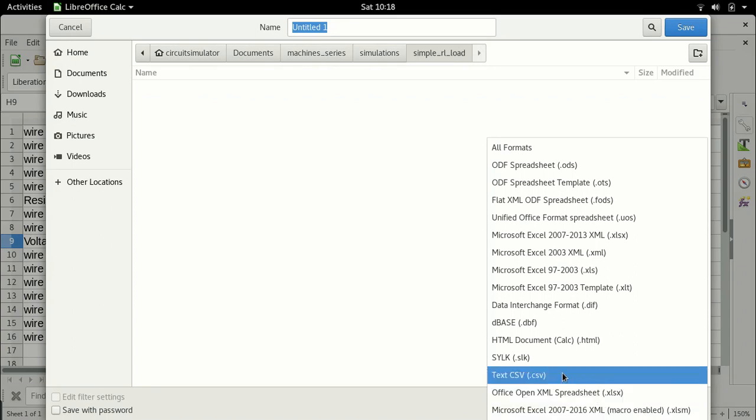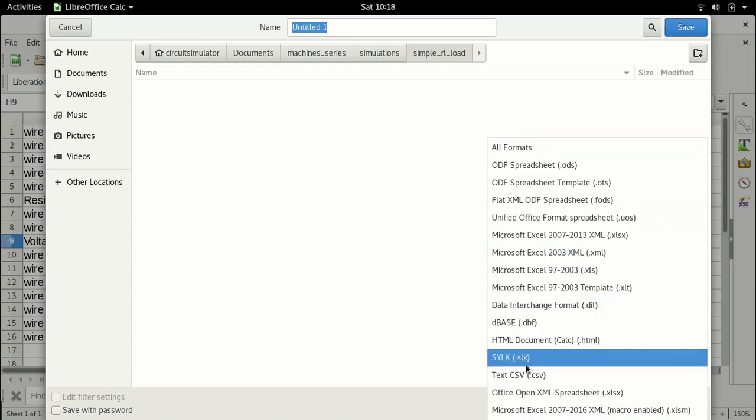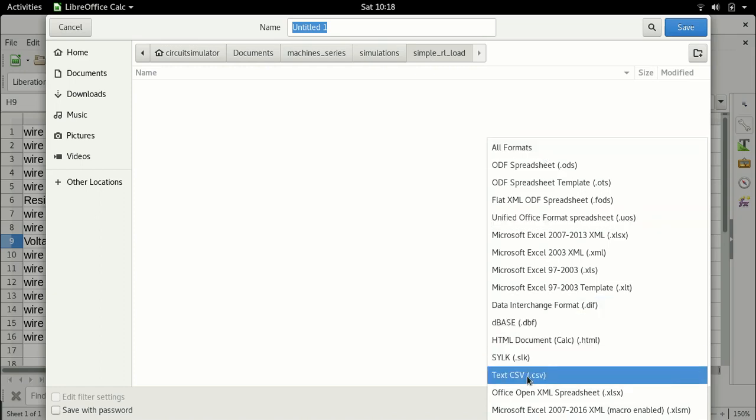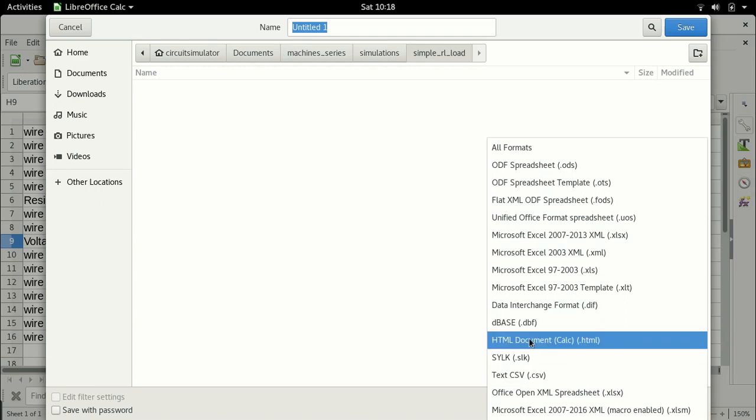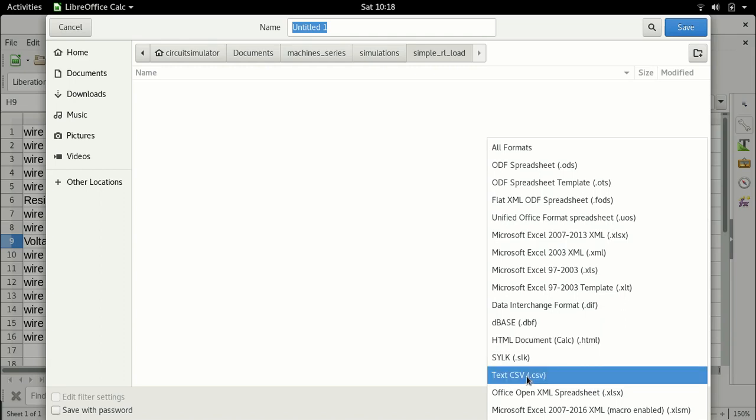and choose text.csv, right? Do not save it as the default value. It will save it as an ODF spreadsheet. If you're using Linux, in Microsoft Windows, you will have to choose MS-DOS CSV, right? Do not save by default XLS. It will not save it. You must save it as a .csv file, which is a comma separated value file. In Microsoft Excel, choose MS-DOS CSV, right?